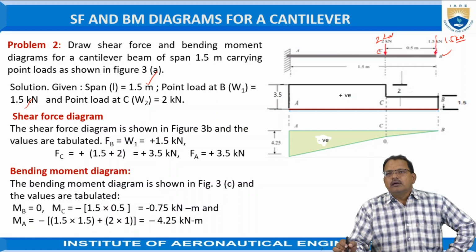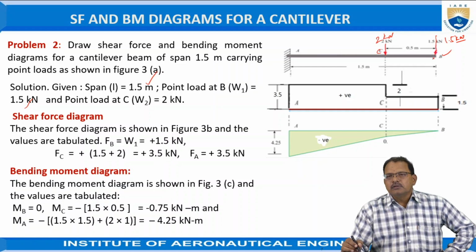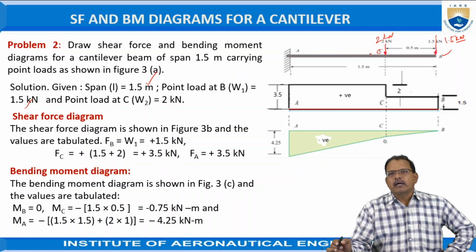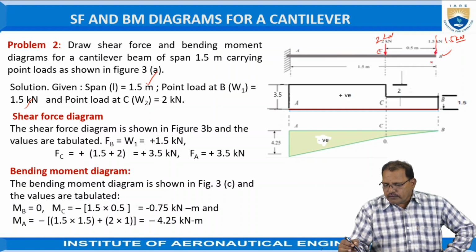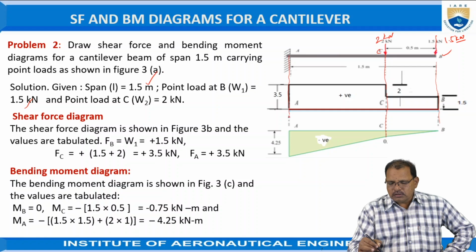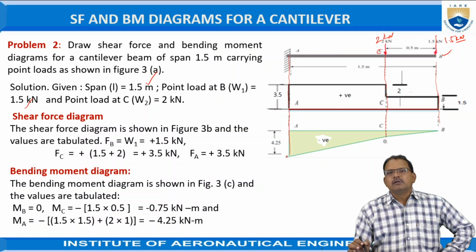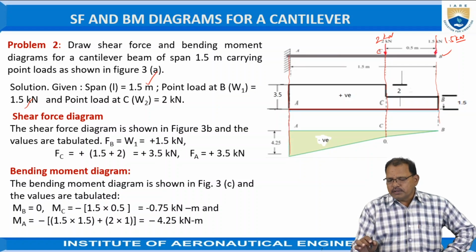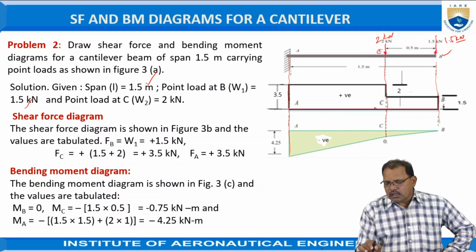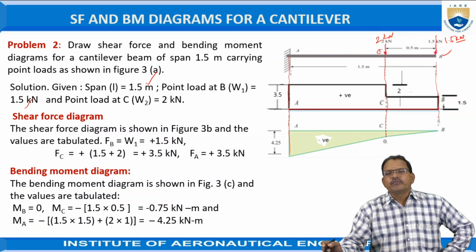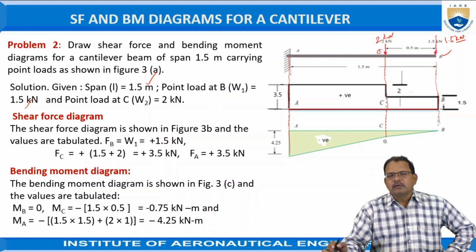Now, in order to draw the shear force diagram for this beam, first of all, draw the beam diagram now. Now, draw vertical lines in downward direction from the various points like this, and one more at this position and so on. Take a suitable gap between the beam and the shear force diagram, a horizontal line representing the length of the beam now.